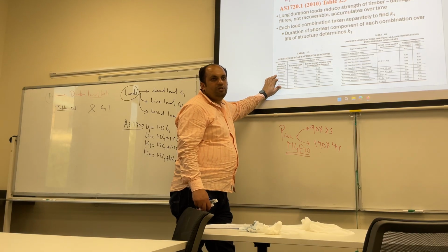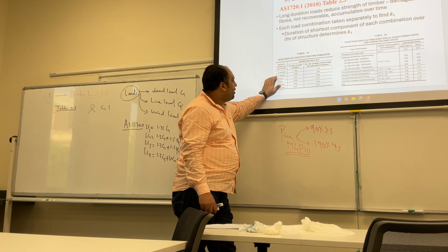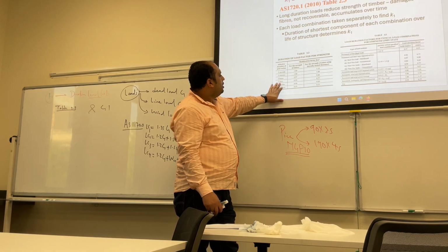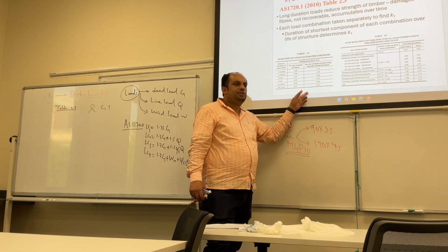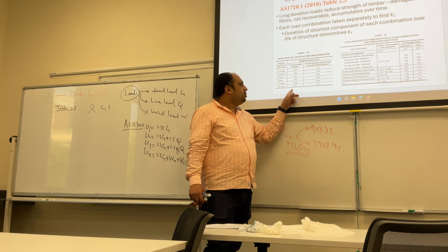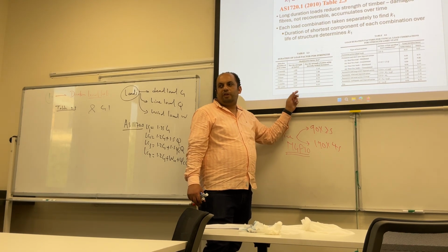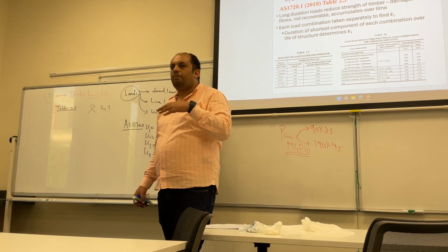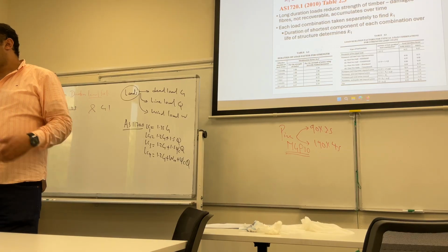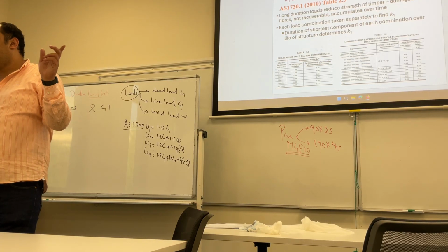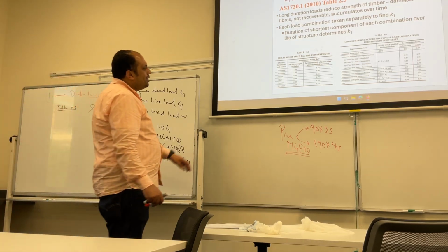So live load also is not for long time, right? So depending on what is the type of live load, it can be applied for 5 days or 5 hours. What is the last one here? 50 plus years. Which load will be applied for 50 plus years? Dead load. So what is the K factor for dead load calculation? 0.57. So the dead load is applied to the building for the whole entire life. So that's why it will cause problem. That's why how much is K1 for dead load? 0.57. Okay. This is for the loads.